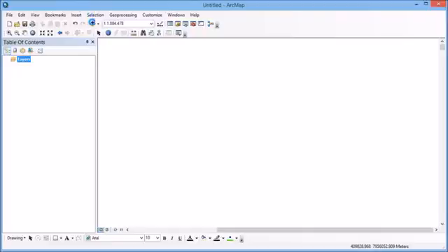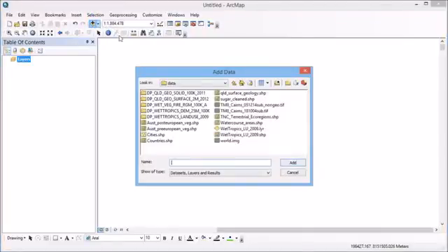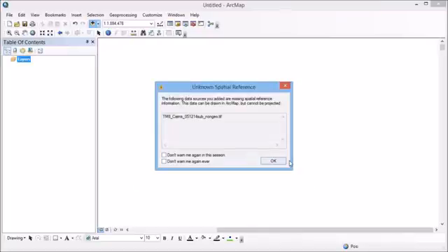So first up, I'm going to open the two images that I have. These are both Landsat 8 images of the Cairns region, one having those coordinates and one without. So we come up with an error in the first place, and this is just telling us that one of the images is missing spatial reference information, which is what we know, and that's what I'm going to fix here. And so that error is okay.